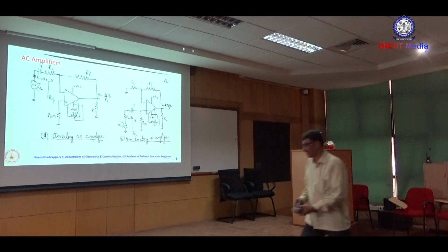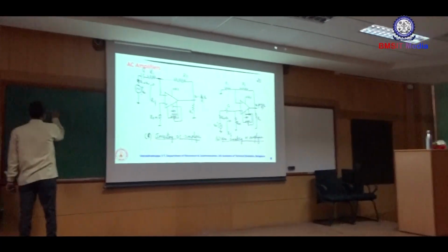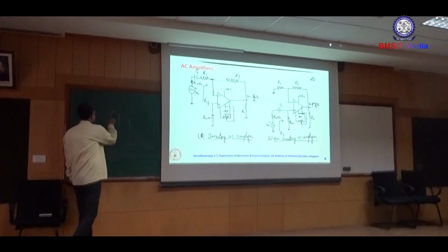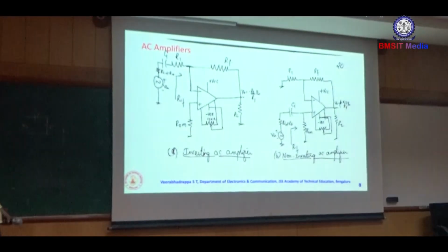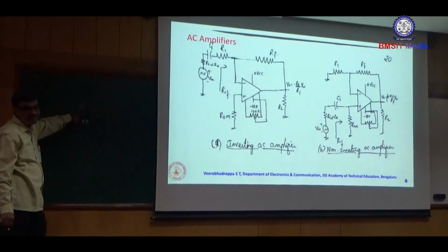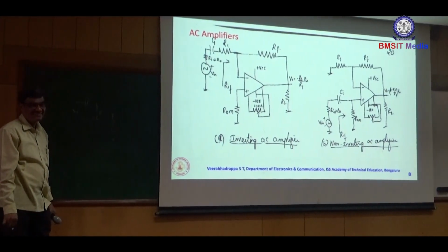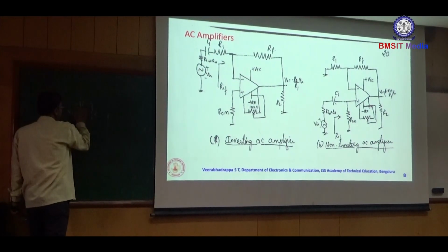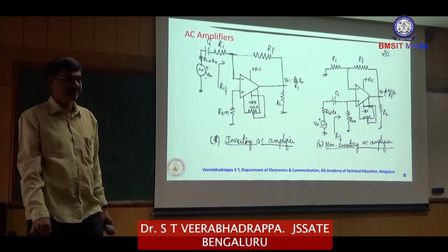Okay, we will consider these two, the capacitor C and resistance R, applying Vn. If the reactance is very high, what is the voltage drop across resistance R? Almost zero, because most of the voltage appears across the capacitor C only.